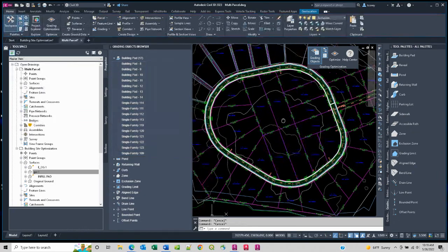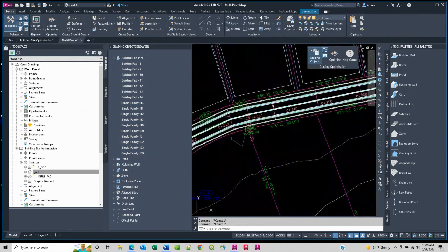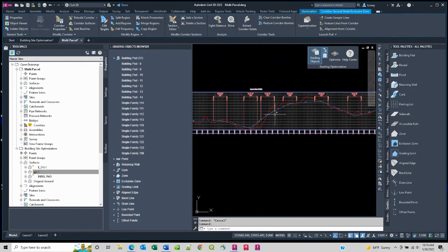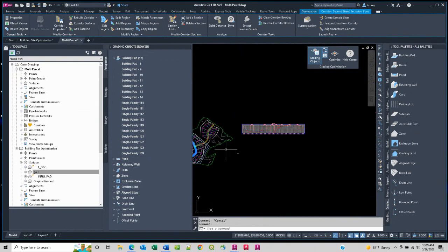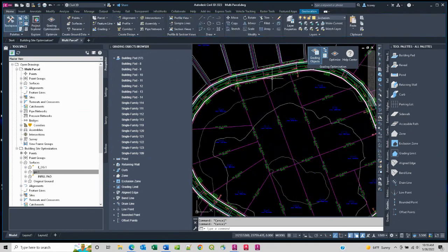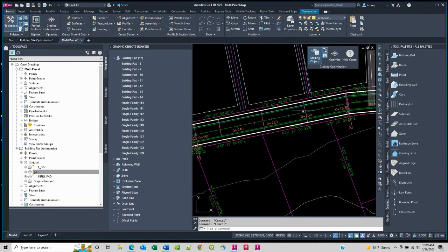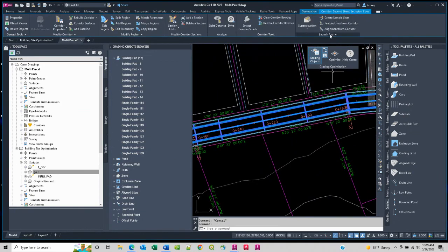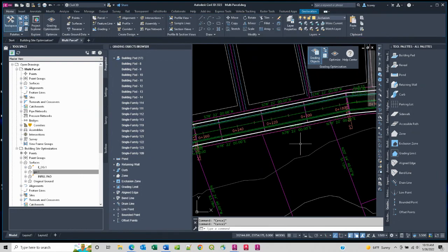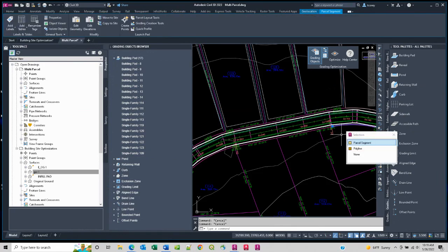Now I've also added in here, you'll see that I have a corridor. This object, which I've defined around this loop, using an alignment and profile over here. There's my finished ground profile around that loop. Okay, so I made the corridor, and then I extracted feature lines from the corridor. I don't know if you're familiar with how to do that. You pick a corridor, and then you go to here, Launchpad, and I extracted polylines from the corridor. That makes 3D polylines. And then I join those up so that I have an enclosed polyline.